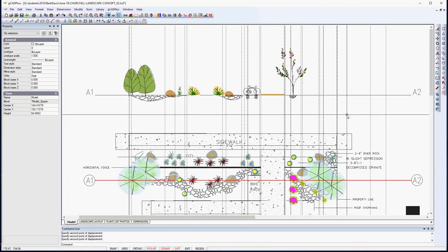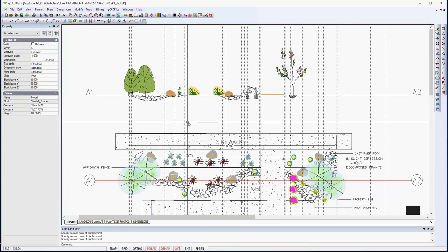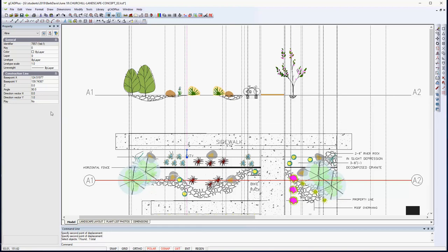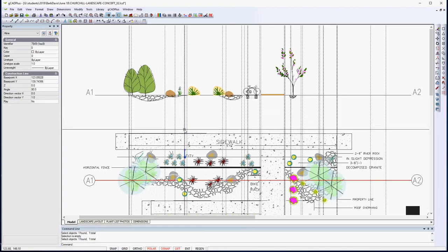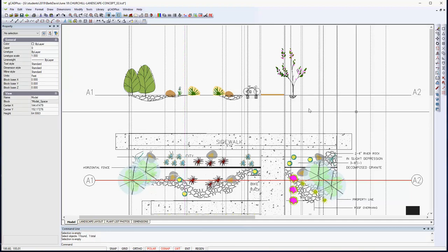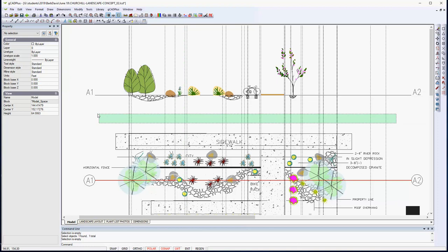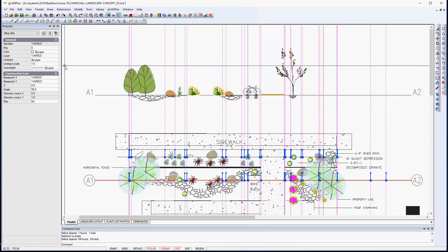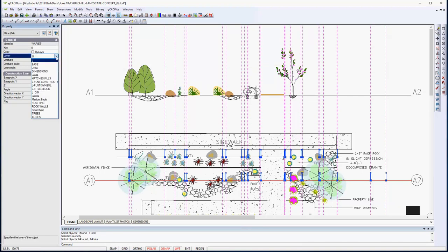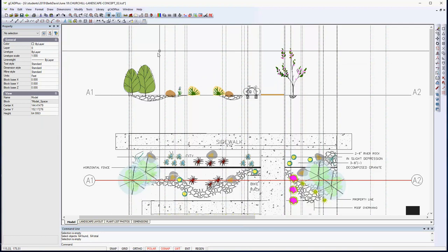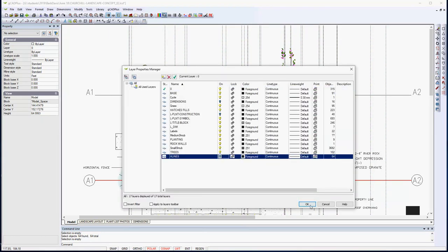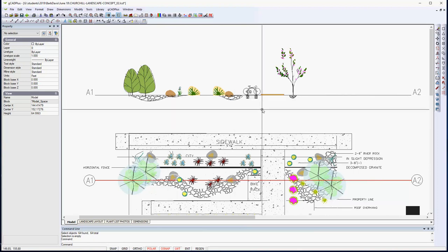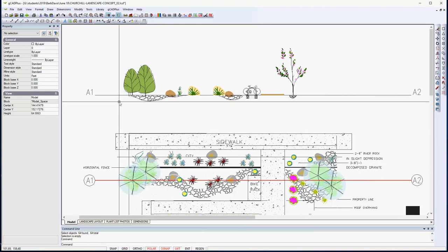So these projection lines are all on their own layer. I'll select one now. You can only pick one at a time. One line there is on layer 0. So I thought we had a layer here. I've just checked, it's called X lines. So now when we finish the section, we can turn off the construction line layer, and there's our section working from a fence.